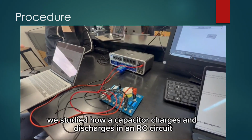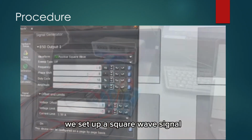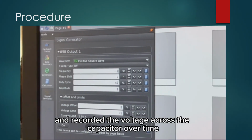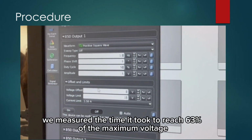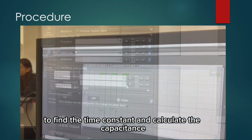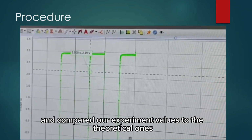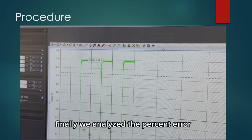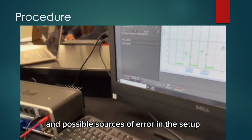In this experiment, we studied how a capacitor charges and discharges in an RC circuit. We set up a square wave signal and recorded the voltage across the capacitor over time. We measured the time it took to reach 63% of the maximum voltage to find the time constant and calculate the capacitance. Then we repeated the process with the capacitors in parallel and compared our experiment values to the theoretical ones. Finally, we analyzed the percent error and possible sources of error in the setup.